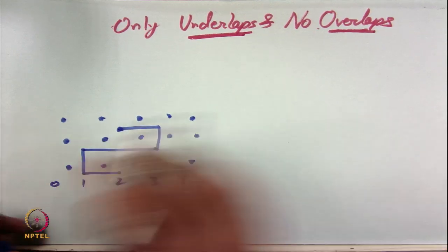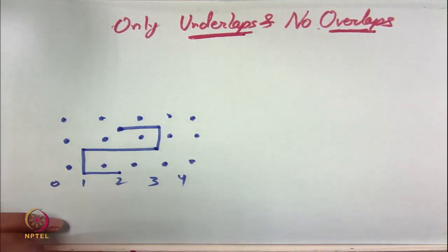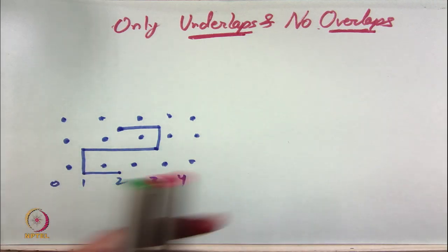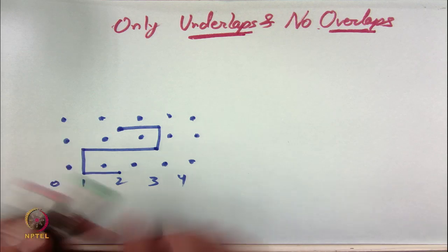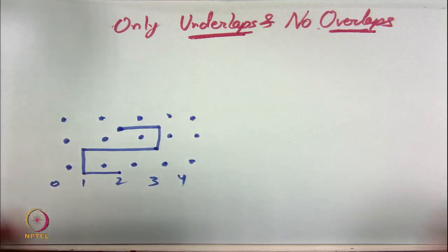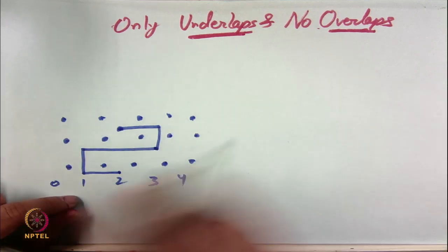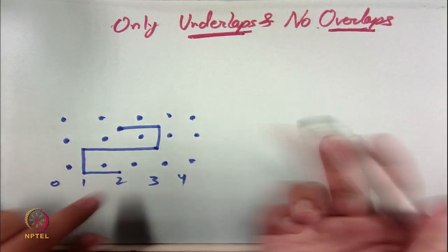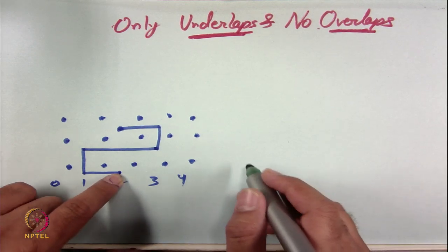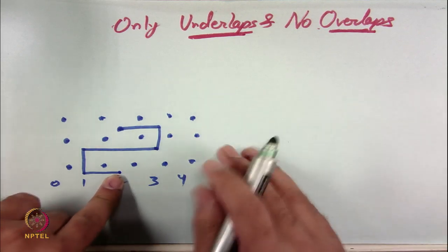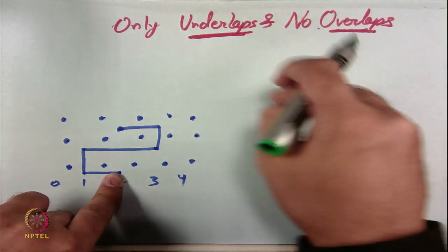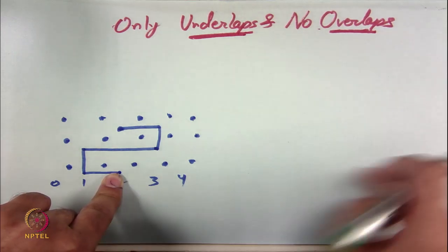So, if you see this, it is just shifting the yarn at the lateral side or the back side of the needle, not providing yarn to the front side of the needle. Because of this, no loops can be created if the guide bar is doing this type of function. So, we can see this. Always, the first thing for any course, it goes from swinging and then overlap, then again swinging, then underlap.